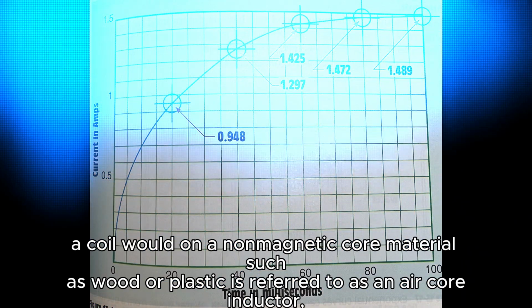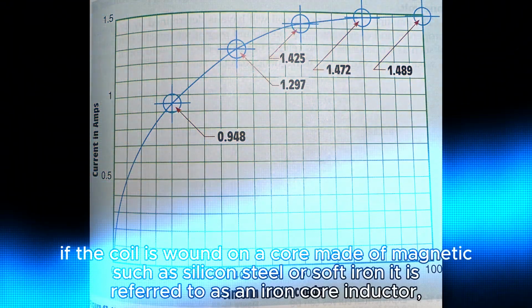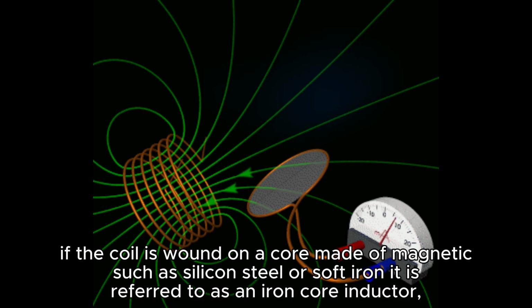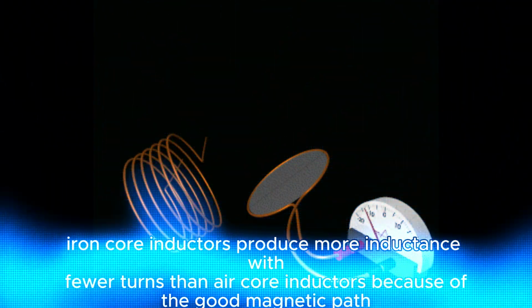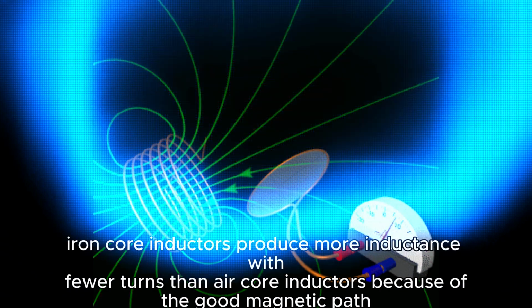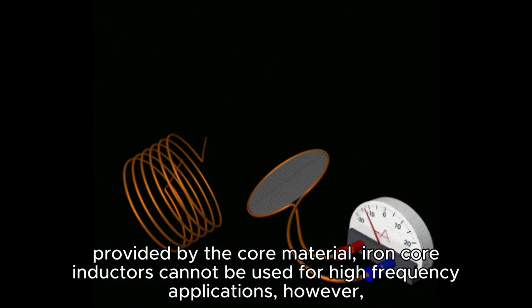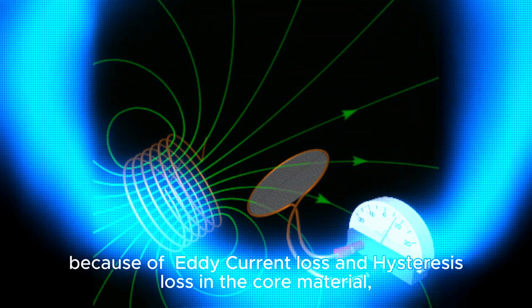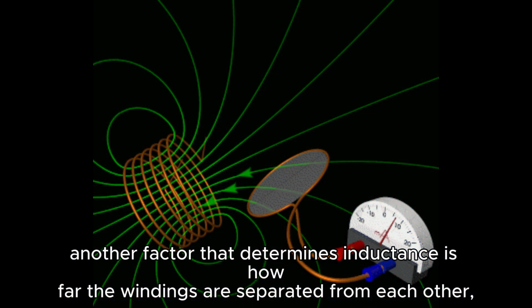A coil wound on a non-magnetic core material such as wood or plastic is referred to as an air core inductor. If the coil is wound on a core made of magnetic material such as silicon steel or soft iron, it is referred to as an iron core inductor. Iron core inductors produce more inductance with fewer turns than air core inductors because of the good magnetic path provided by the core material. Iron core inductors cannot be used for high-frequency applications, however, because of eddy current loss and hysteresis loss in the core material. Another factor that determines inductance is how far the windings are separated from each other.